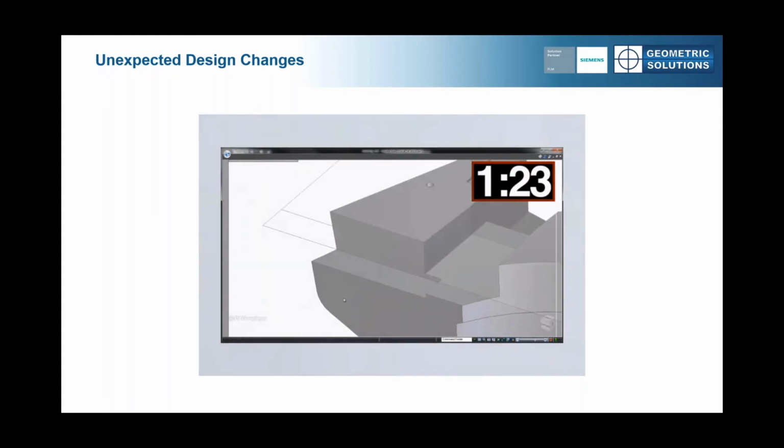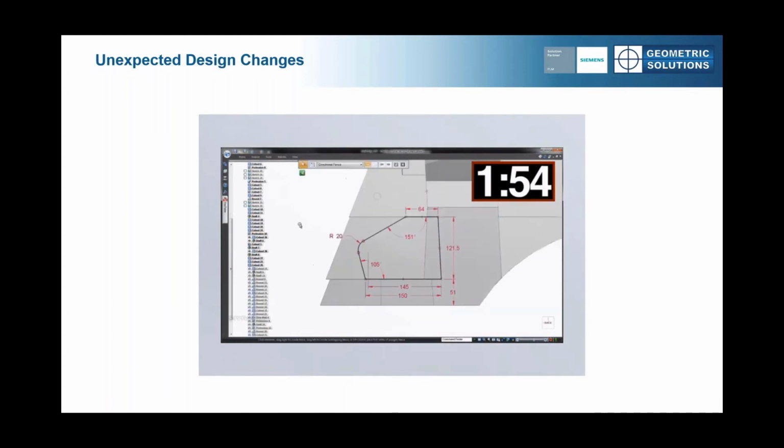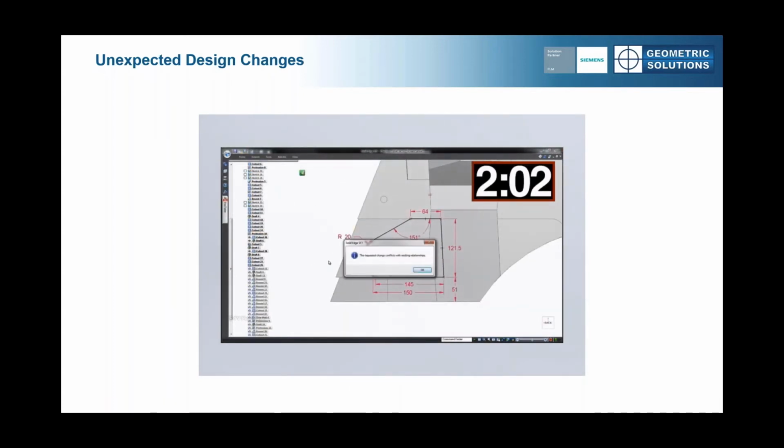As we edit the top feature holding face A, because history-based CAD is order dependent, the cut below that holds face B doesn't yet exist, so we can't match to it. Therefore, we have to do some drag and drop reordering in the tree so that we can see what we want to match to. Oh, and notice some grey arrows that have just appeared in the tree.